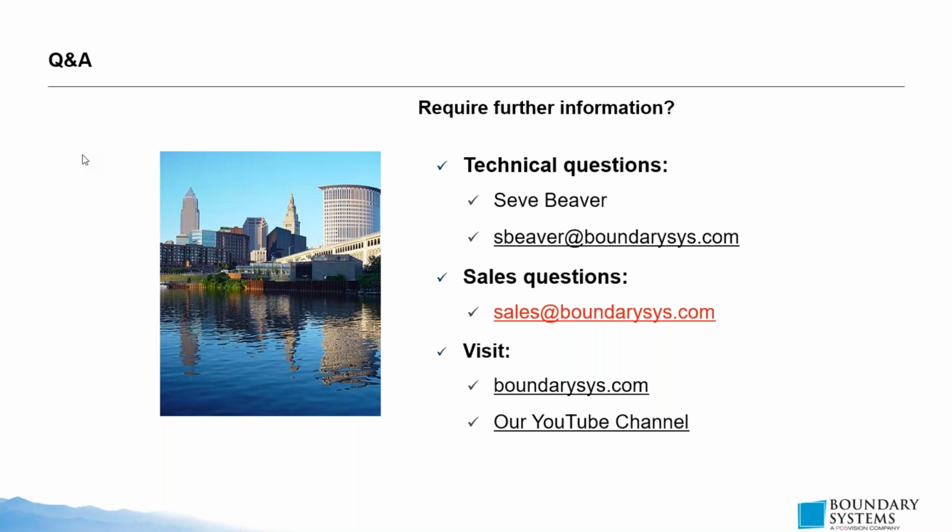Let's see what else we got here. Can the K factor be adjusted? Yes. So this is relating to how Creo calculates that length. Essentially, it's going to change every time you make a bend or something like that. And it varies per material and also due to specific manufacturing processes as well, which is why people might want to customize that.